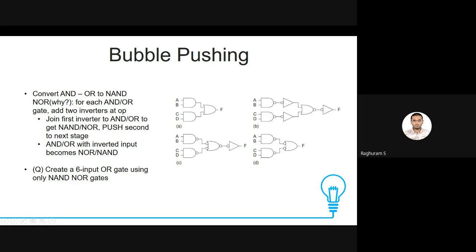Okay, so we have the NAND gates here, and this thing has combined with each other, and in the output of this we have two inputs that are coming here. These two inputs together with this OR gate make this also a NAND gate. So that is what you see here. The OR with the inverted inputs is actually a NAND gate.